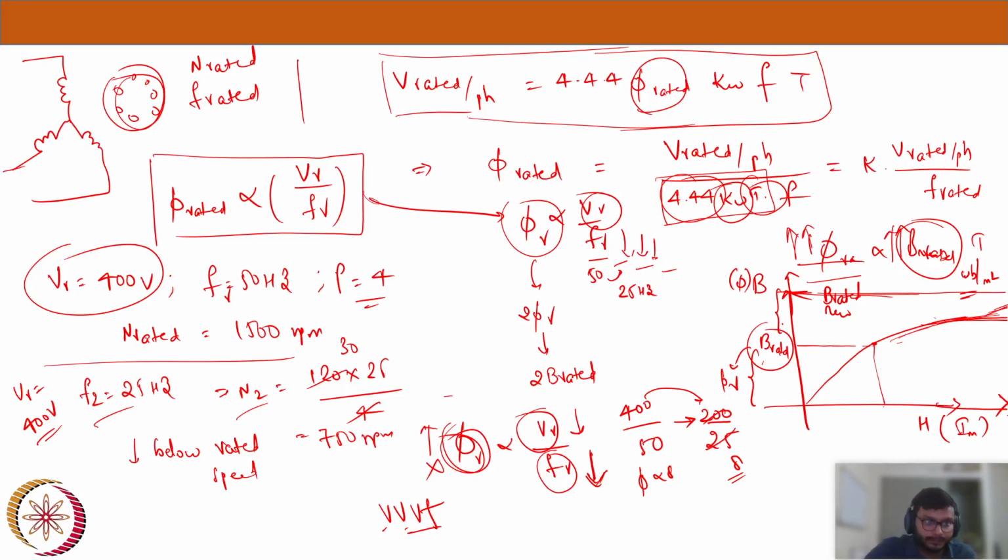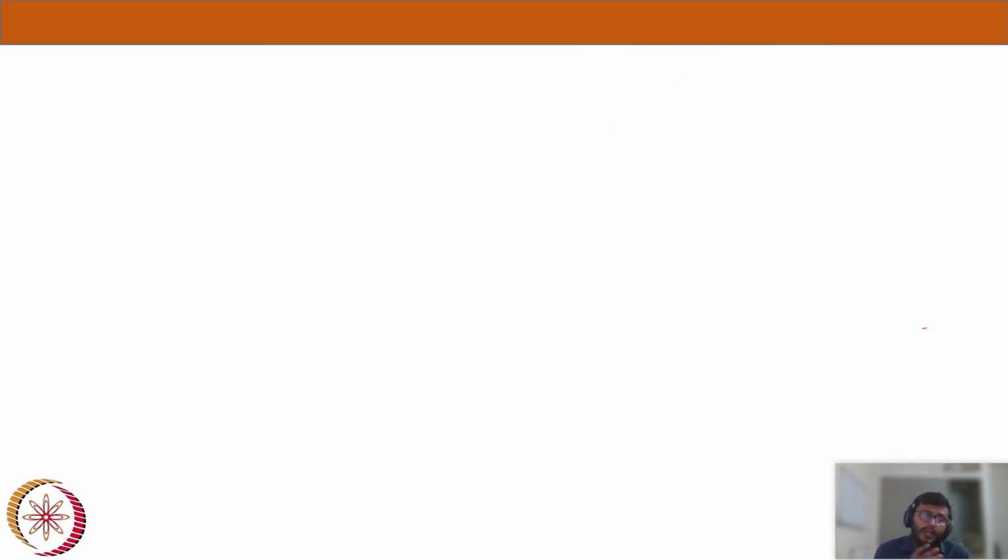So that's the question. Now we know some approximate equations which we derived 2 weeks back for the torque and also current equations, which we have approximately derived by neglecting the rotor and stator impedances. If you remember that, we have solved many numericals also. So if you remember the torque formula, torque is equal to some constant K multiplied by S alpha by S square plus alpha square.